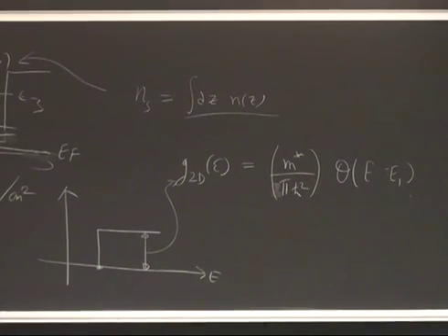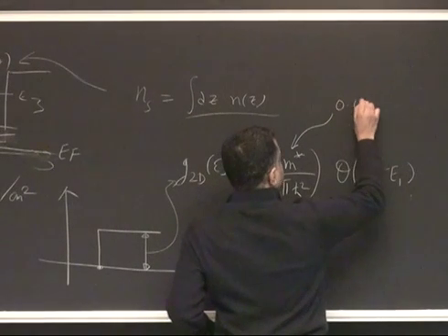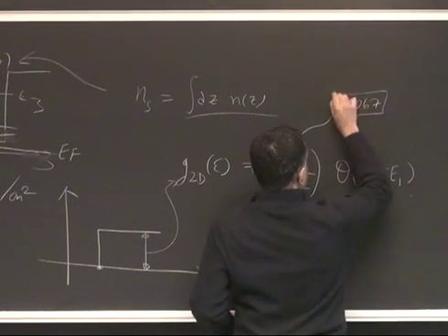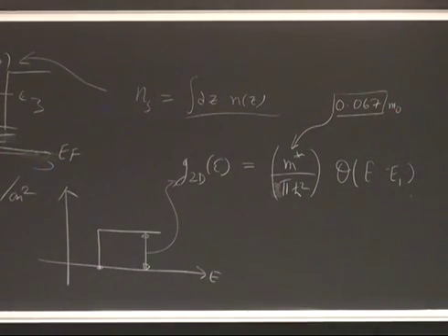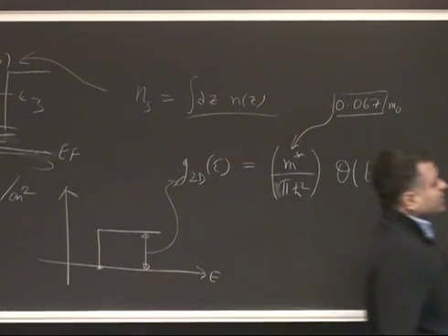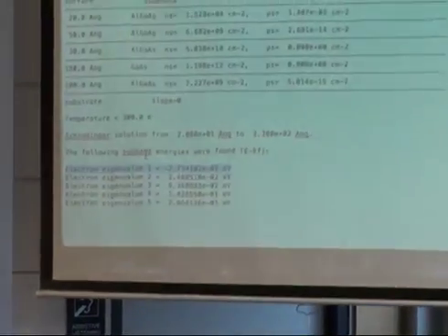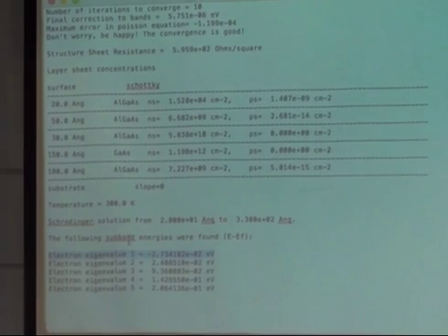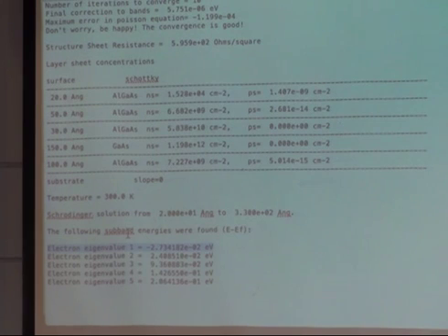And this height is the density of states of a 2D electron gas. Now, because you know that the 2D density of states will look like that, and we're looking at gallium arsenide, which has an effective mass of roughly 0.067 times m naught, the free electron mass, you can plug that in. Just as a back of the envelope, I have 2e12 per centimeter square carriers in the well, and there's only one subband filled, right? So where is my Fermi level with respect to E1? The 1D Poisson and Schrodinger solver told you it's 27 meV below. But can you do it analytically? And the answer is yes.